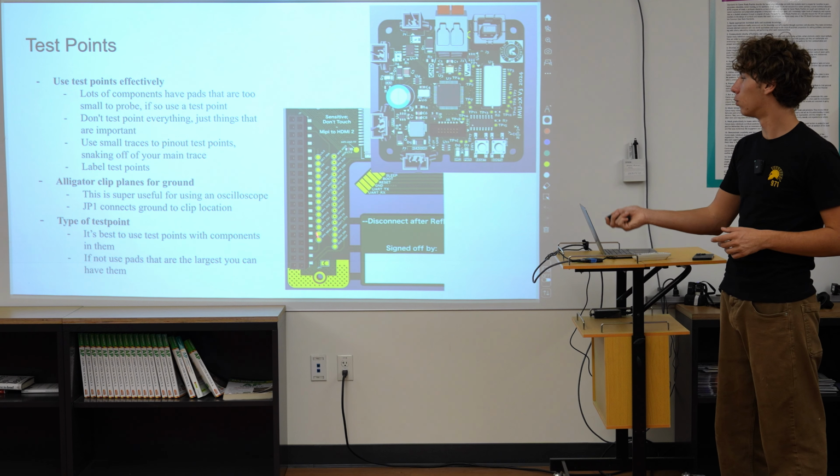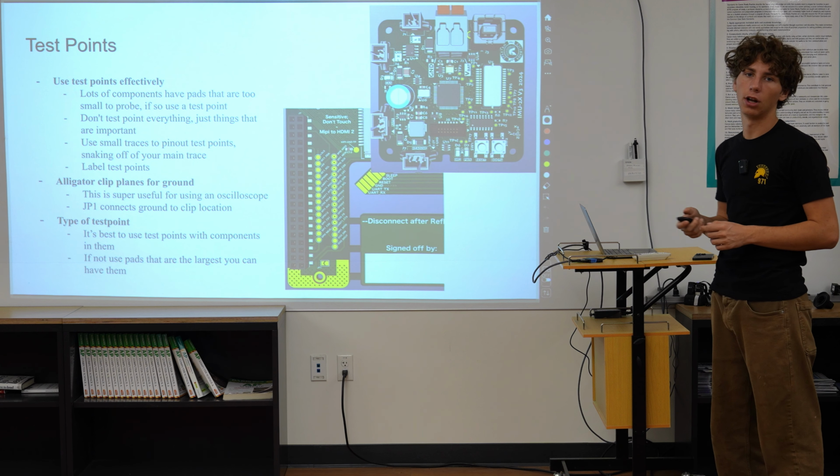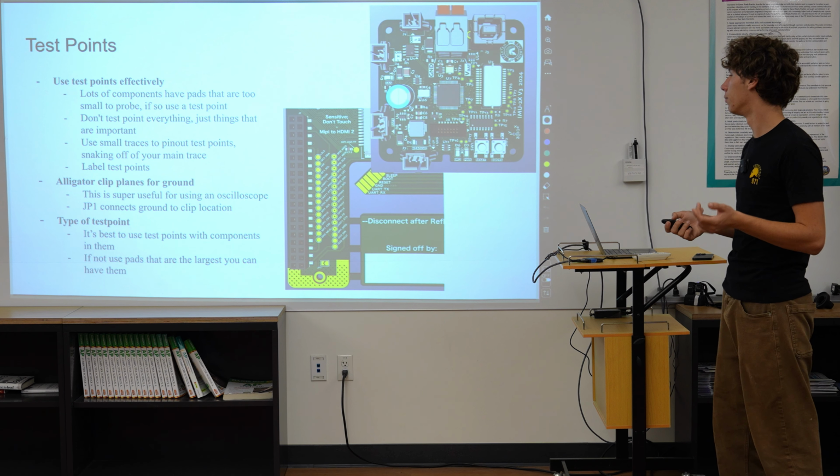And then label test points. Over here we have them labeled with what they are, and over here we have them labeled with numbers, and then we'll have a spreadsheet on what they are that we could probably just print out if we're debugging.